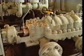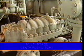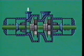That's where multi-stage pumps come in. They have two or more single-suction impellers mounted on a single shaft. The discharge port of the first impeller is directed to the suction port of the second, and so on through additional stages. When the fluid flows from one stage to the next, fluid pressure is increased.